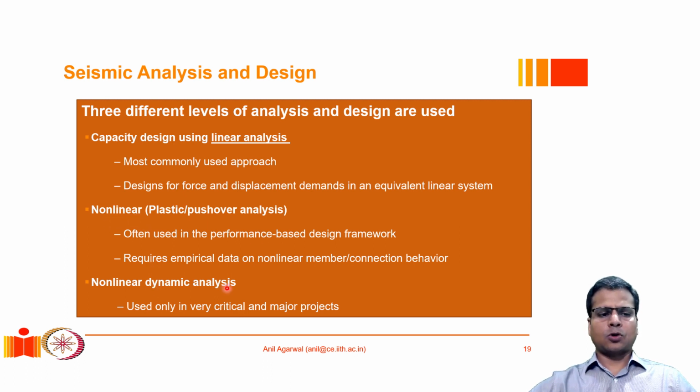The third and the most complex one is known as nonlinear dynamic analysis. In the second one, even though we were accounting for the plasticization of the structure, we were not really accurately accounting for the dynamic aspect, the time variable aspect, of the earthquake. So in a pushover analysis, we keep pushing in one direction in a monotonic way, which tends to simulate the most severe earthquake, but does not really simulate the earthquake properly.